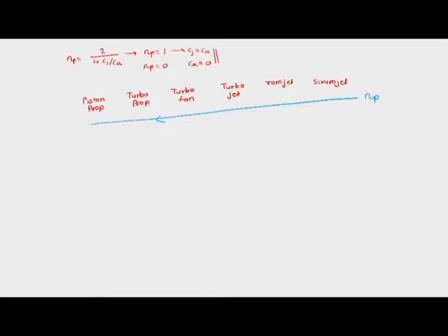Here we have to understand that thrust is gained through two things. The thrust formula was m dot into Cj minus Ca. So thrust is gained by an aircraft for a given mass through the change in velocity between inlet and outlet. Some aircraft have a very large value of Cj minus Ca.